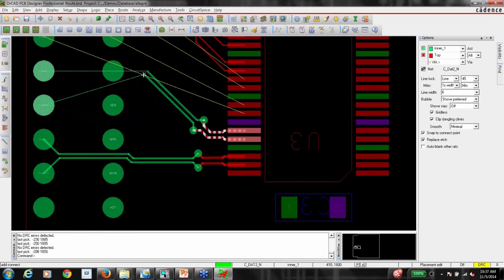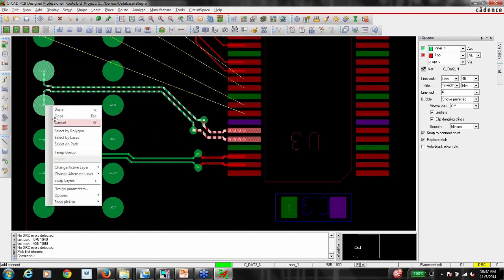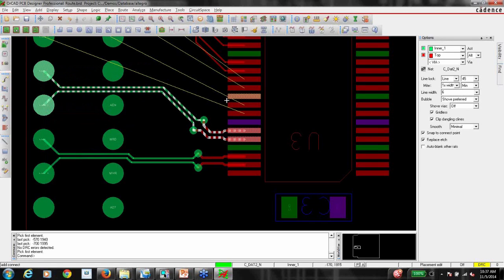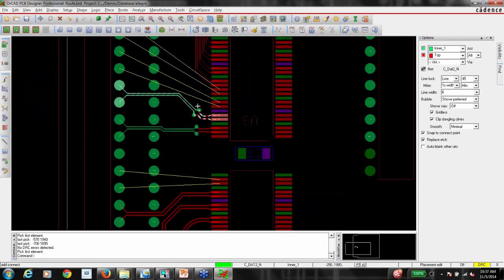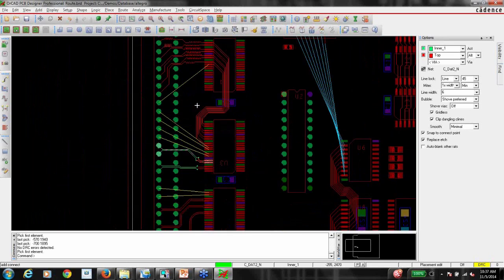Sometimes if you have a tight phase tolerance, though, assuming you have Allegro PCB Designer, you can end up with some phase issues using the diagonal. It just depends. So that's some differential pair routing.